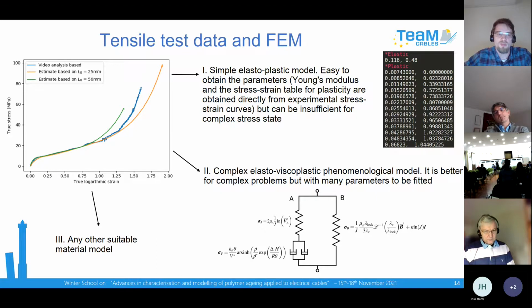And if we consider polymer, the stress-strain state in the polymer matrix will not be just uniform tension, but it can be much more difficult. There are some tensions and compressions in different directions, even though we only apply tensile loadings, because of the complex geometry of the specimen, I mean microgeometry.